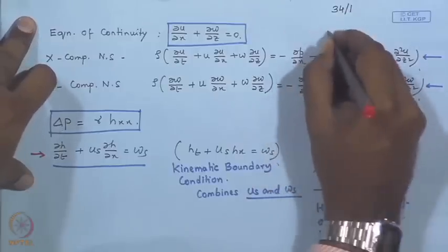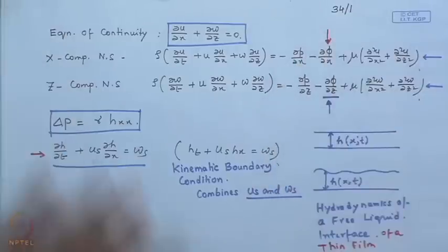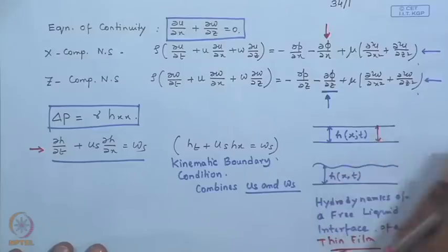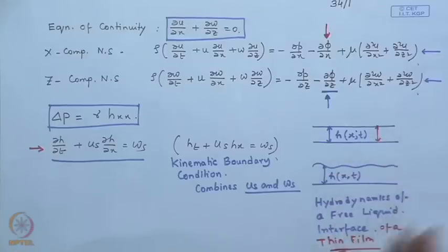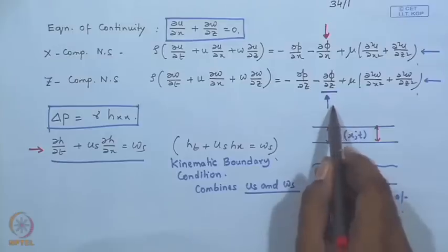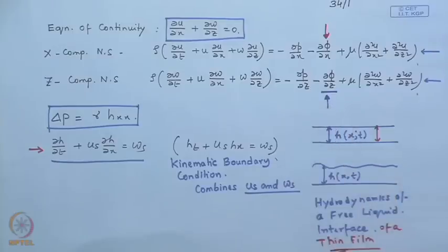The only additional terms you find are the effective interface potential, or the phi, which arises out of the interfacial interaction between the two interfaces, because we are talking about a thin film. This interaction, which can be van der Waals or other forces, will be taken care of through the expression of phi. So, please understand that in the present form, the Navier-Stokes equation is not limited to van der Waals interaction alone.